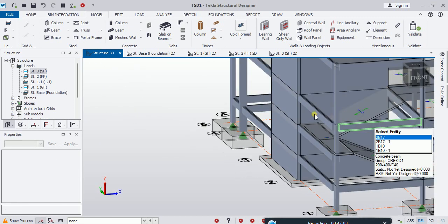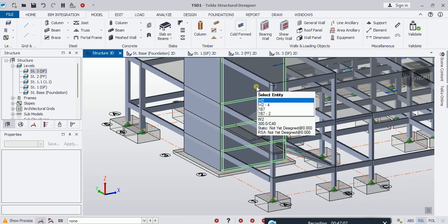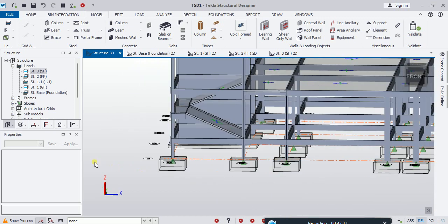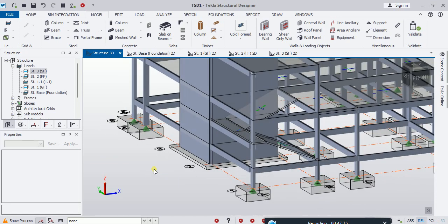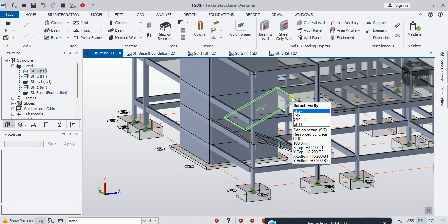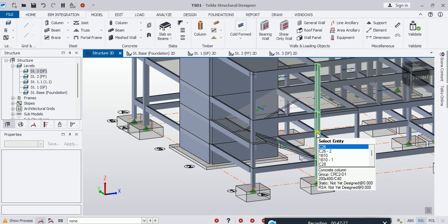Okay, so you can draw beams in order to help you in whatever direction you want. It will make your work easier. So I kept drawing, and you can see that this is your stair. Are we clear? Okay. Do you require landing here? At the top, do you require landing? Because it's directly the floor, right? We don't require landing. Do we require it here? No, because actually there is a ground floor.